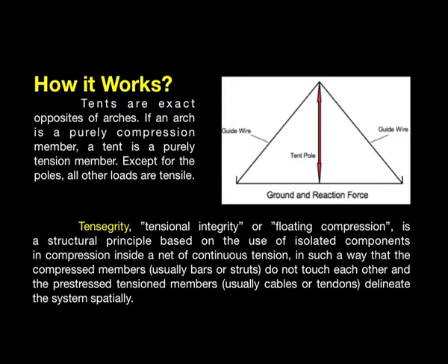In tensegrity structures, there are usually more of these struts, and they are arranged in such a way that none of these struts actually touch each other. It is essential that we understand this because a very early, rudimentary form of a tensegrity structure is what is expressed in the form of a tent, because there are 2 poles acting as struts which don't touch each other, and these struts are entangled in the guy ropes, the fabric, and the other elements which make the tent.